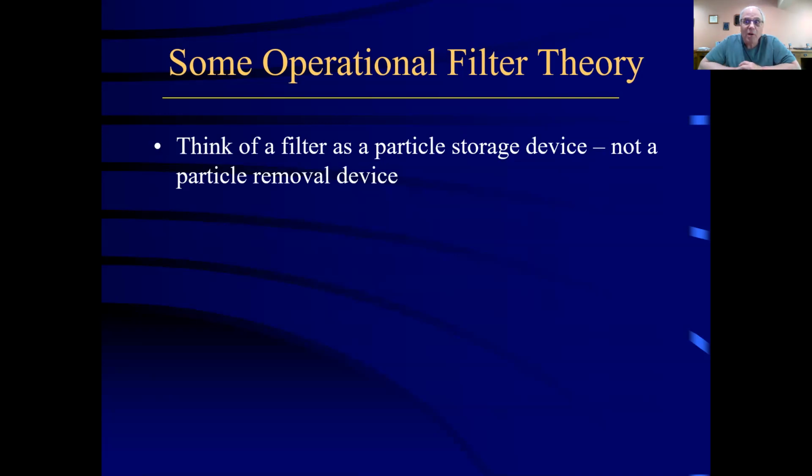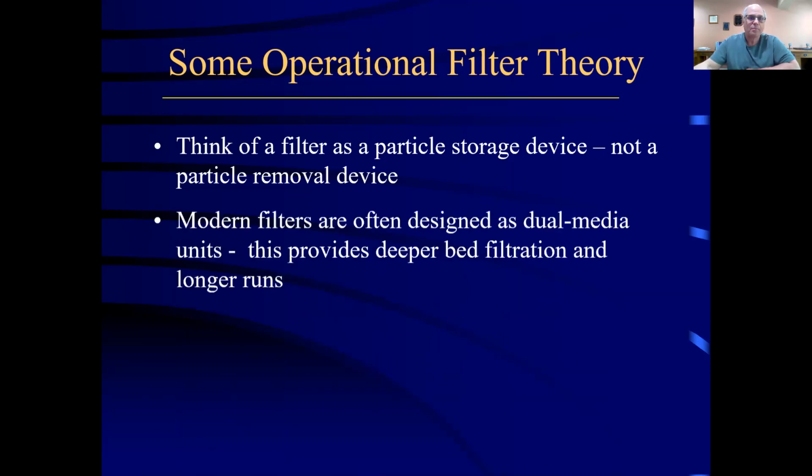The longer you run that filter, the longer you're storing those particles, the greater chance you have of having an upset in that filter and washing all of those particles down into filtration or down into the disinfection area. You have to be very careful with storing these particles. While you're doing that, try to be very careful with your filters.